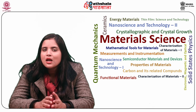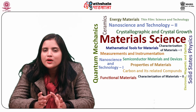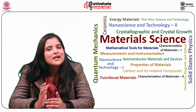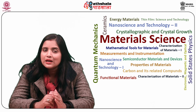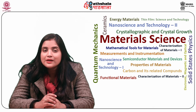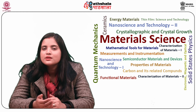All of them had rectangular cross-sections with widths between 30 and 300 nanometers, width-to-thickness ratio between 5 and 10, and lengths of a few micrometers. All the semiconducting oxides exhibited belt-like morphologies.